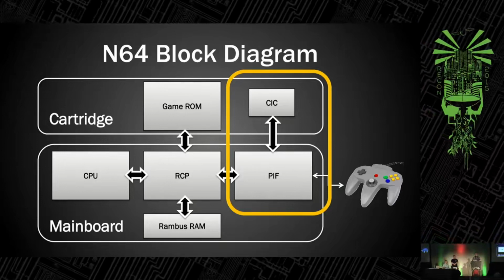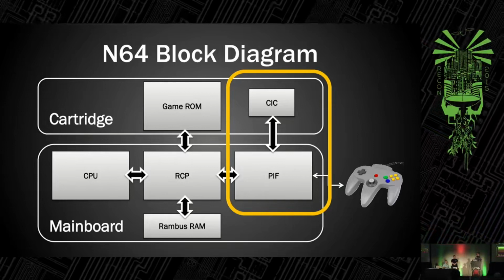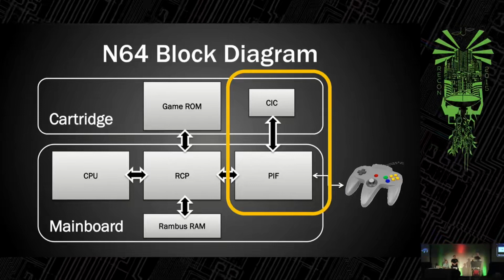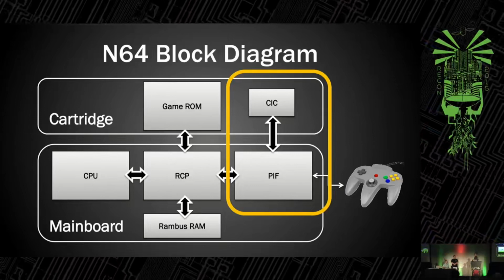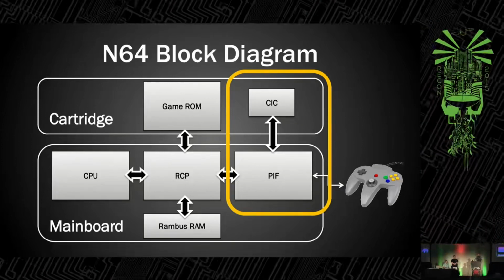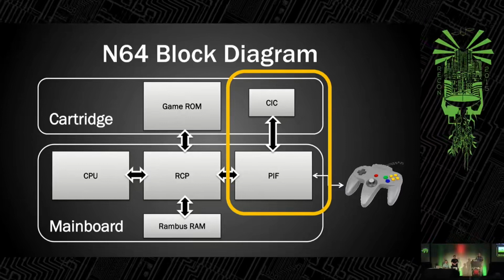Same deal. These two chips are talking to each other from the moment you turn the game on until you turn it off, always talking to each other. But instead of being two symmetrical things executing in lockstep, the PIF is just rolled into a chip that handles all the system bring up and polling the controllers and the interrupts, the resets, and all that sort of thing.